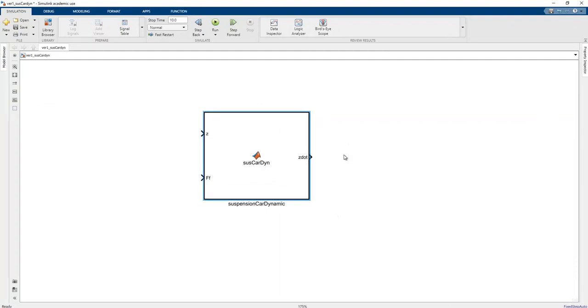Okay, and so how can we create proper dynamics in the Simulink application? In the Matlab Simulink application, everything is the operation of the iteration process, which means that any number or value is created for an instantaneous time, or at each time. Okay, and so if you have an equation of motion like this one, state space representation, this is the derivative of z, and so we need to obtain the z value by using these things, because this is the dynamic equation of motion of our study.